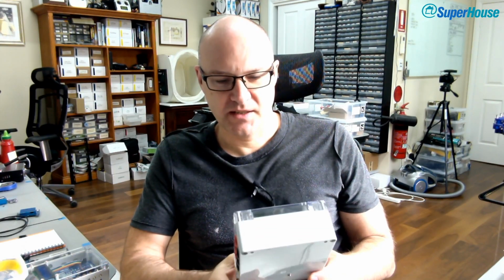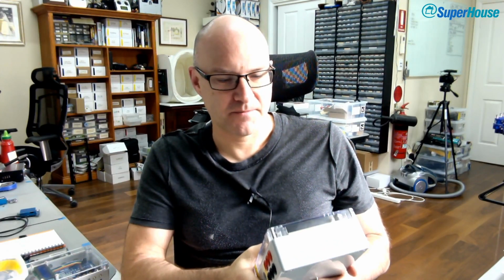So what is in here is quite simple, really. There is a little stack of boards in there. It's a bit hard to see, but there is an Arduino down the bottom. I think it was a Duemilanove. Then in the middle is a Wi-Fi shield, and then on top of that is a prototyping shield, which is just used for some connections as a breakout essentially. And you can see there's a chip on it right there. That's a watchdog timer. So that's a 555, and if the device fails to pat the watchdog, I don't remember what the timeout was on this, it was probably like 2 minutes or 5 minutes or something, then it would pulse the reset pin and force the device to reboot, and that allowed it to recover from situations like power outages and problems with Wi-Fi, because this was using Wi-Fi to connect to the house that we installed it in, so it could recover.